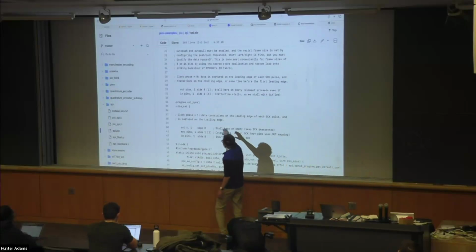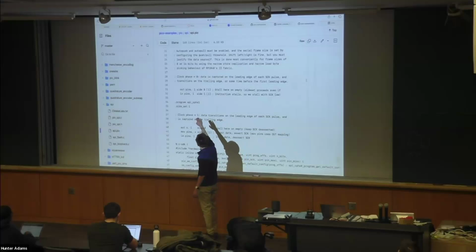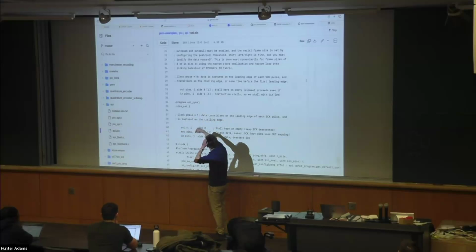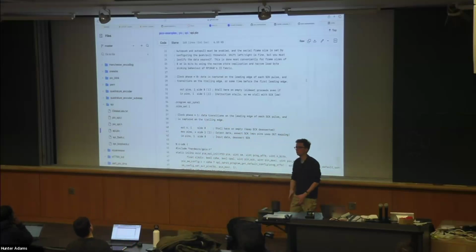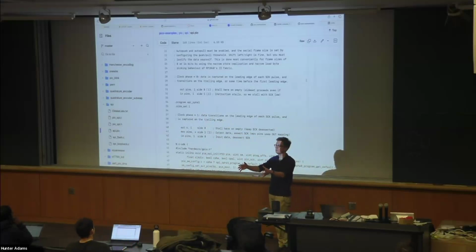And we're saying we're going to have one side set pin. This program starts on an out instruction. Out pins 1 means please move 1 bit from the output shift register to the pins. Oh, and when you do that, please toggle the side set pin low and stall for 1 instruction. So we plunk some information into the TX FIFO, right?